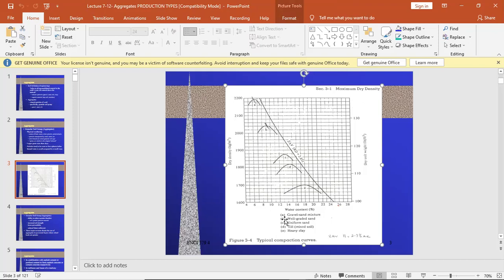Whenever you have fine aggregate in your gradation, it will absorb asphalt. And if you have a coarser type, it will absorb less asphalt. So if you have been asked, in a mix design with 4.5% asphalt content, and you have designed 4.2% asphalt content, what should the gradation be? What should the gradation be like?